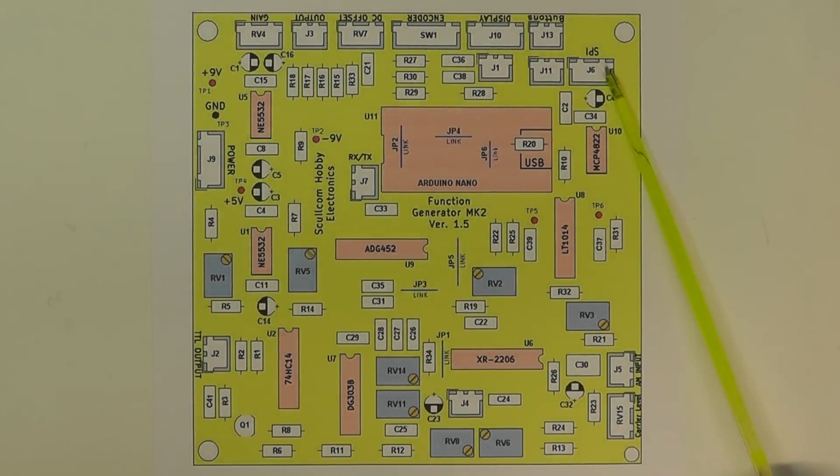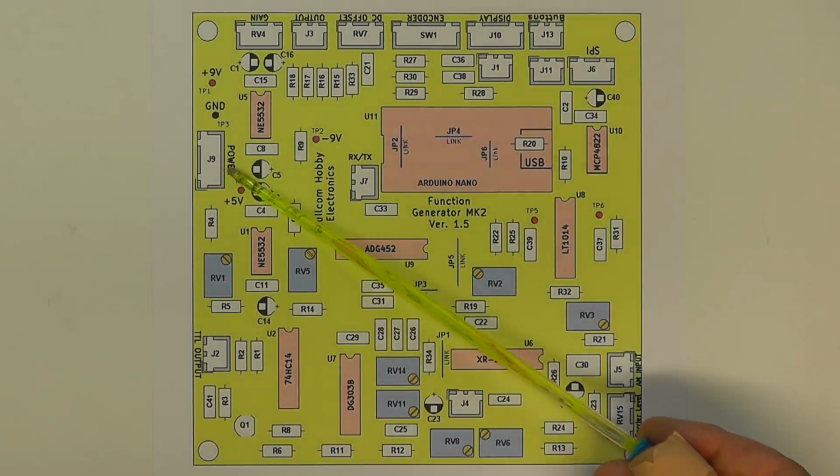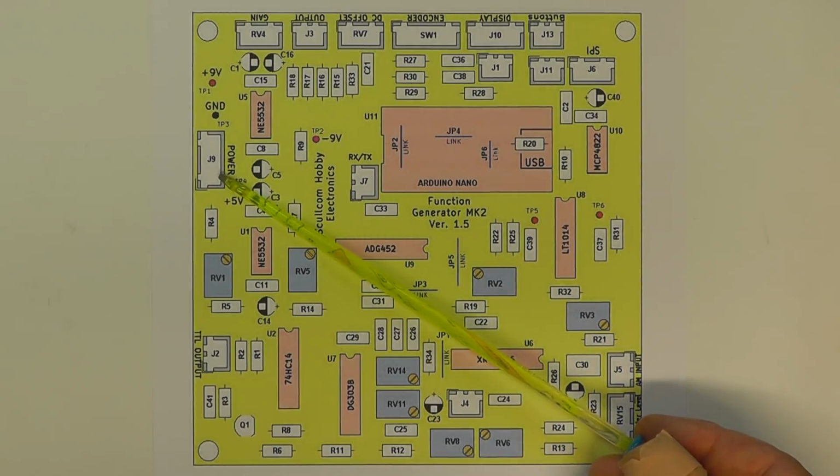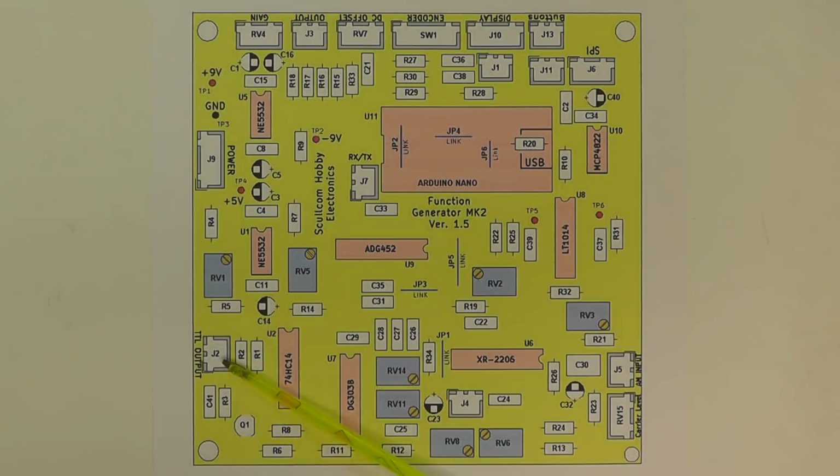Now, some of the other sockets I've provided: there we have the power supply connection to the board, and I've also got the TTL output there, which we may have on the reverse of the case, so that's why I've situated that towards the back of the PCB. And also, on this side of the board, I've got the amplitude modulation input and the carrier level for that. Again, I've put them at the back of the PCB because that may be a feature we want to have on the back of the project case.